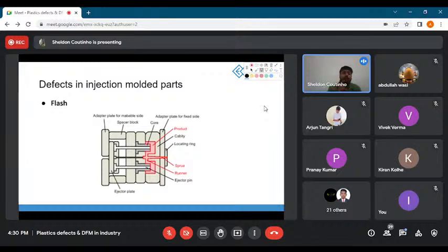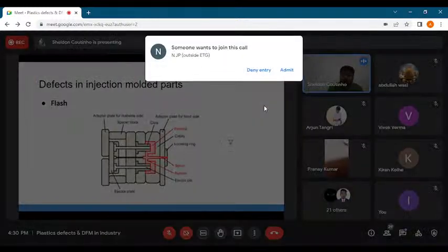So next, coming to Arjun's point, and that would be mismatch. Mismatch was a very big concern in the past, where people had not nailed how to manufacture molds properly. Today it's not that big of a concern, because the machines have improved, the mechanisms have improved, and also you have something called guides or locators. So basically, you have locators for your plastic parts.